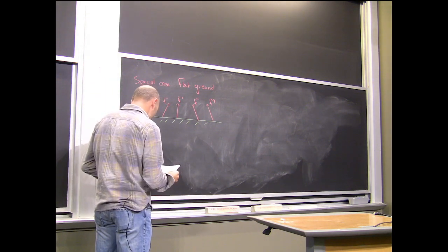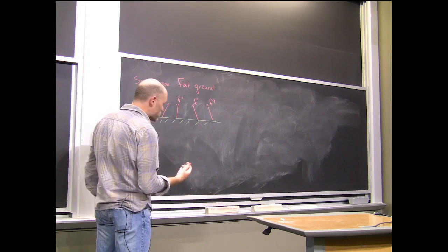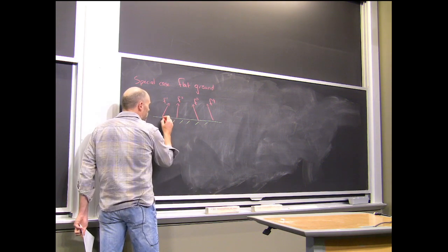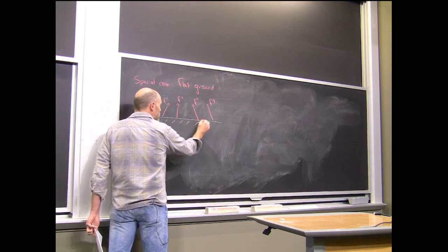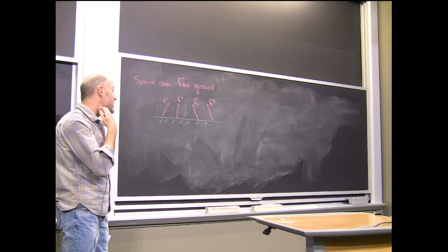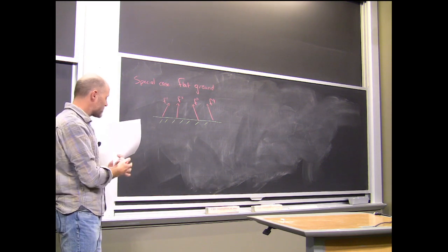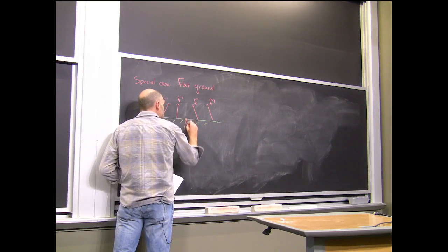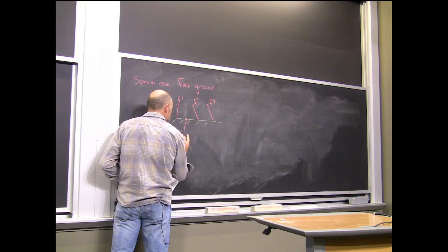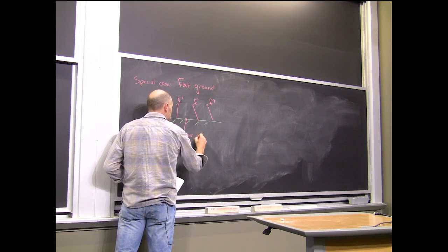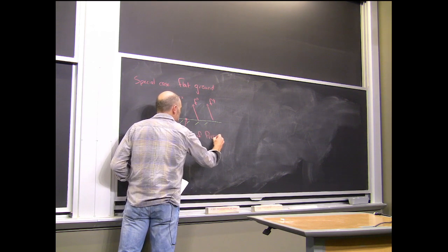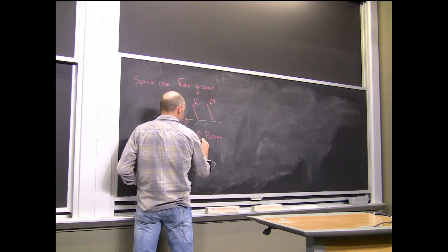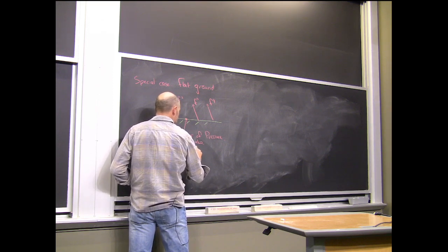Okay. The punchline, just to give it to you first, is that I can summarize the total effect of these forces on my center of mass dynamics with a single point, which is going to be the center of pressure. In this case, it's equivalent to the zero moment point.